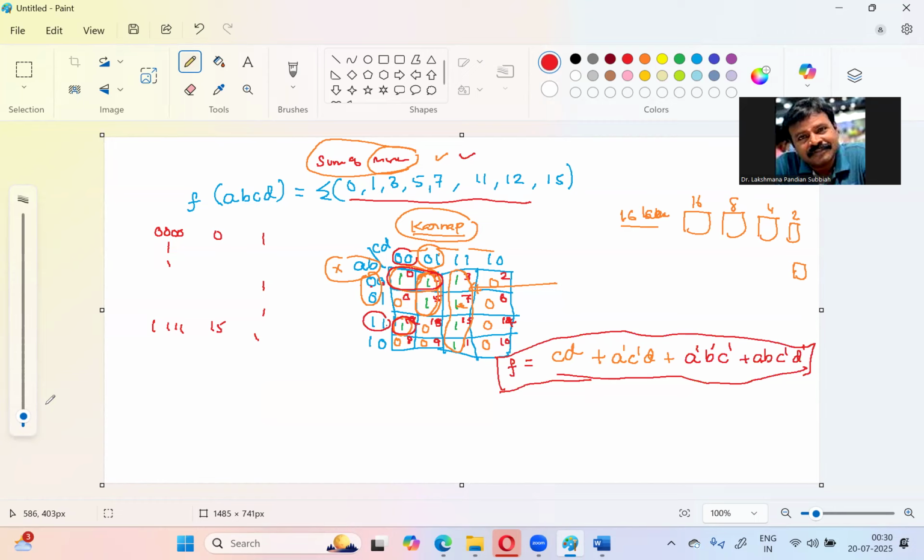So how do you draw the Karnaugh map if they give the sum of min terms? They will give the variables and then sigma. Sigma is called sum of min term. The min terms are given as the corresponding numbers. Otherwise, they may not give the variables, only the numbers. The maximum of 16 numbers means 4 variables, 8 means 3 variables, 4 means 2 variables, and so on.